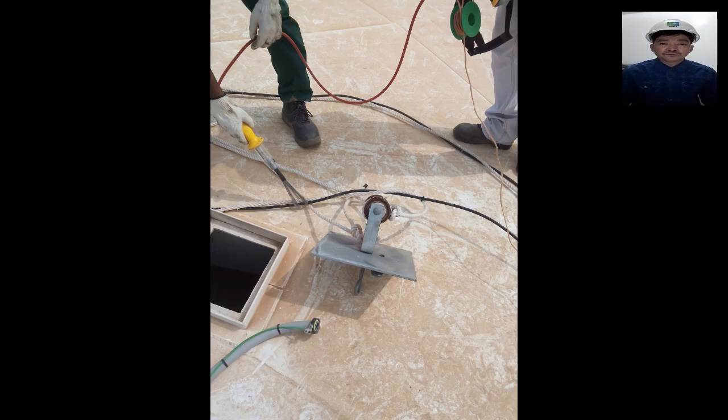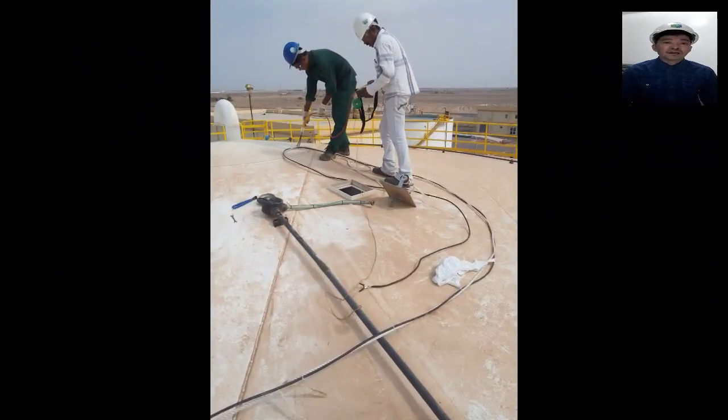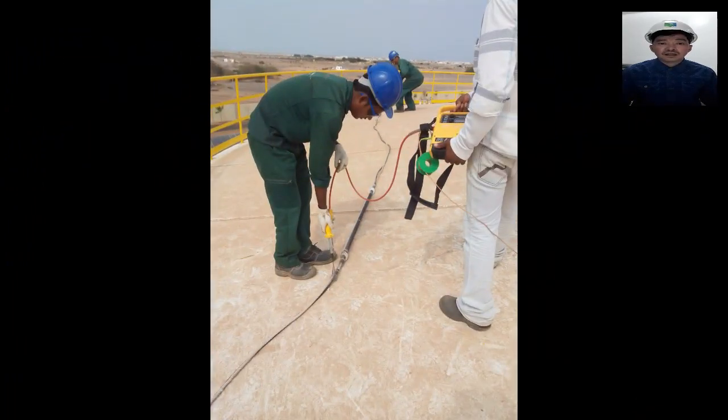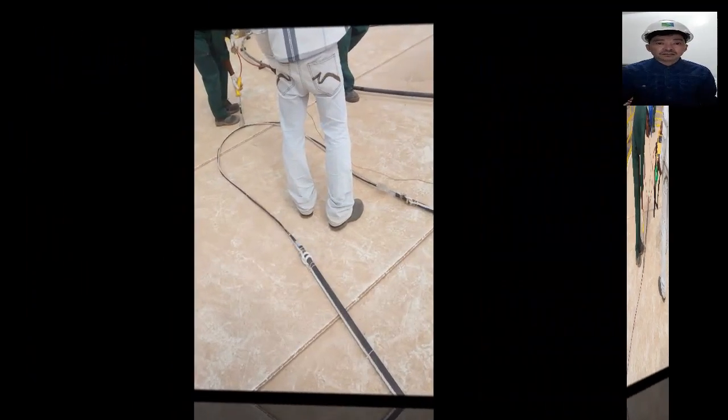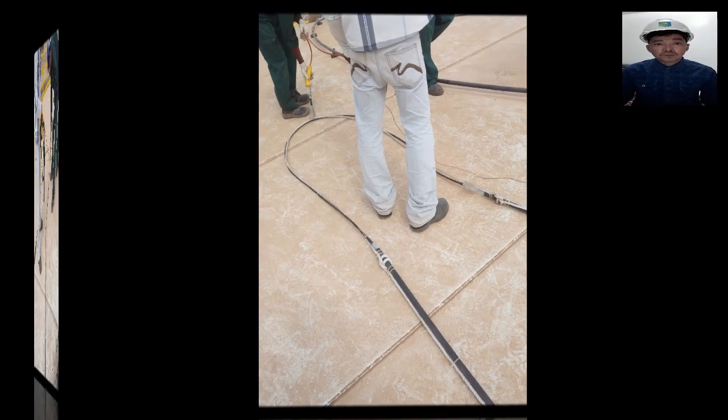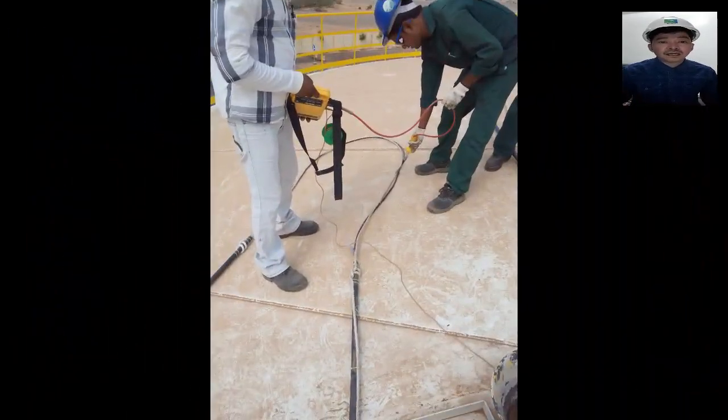That's why during the design, the length of the cable is measured already, and it is as per plan. That's why the distance of the transformer from the tank is normally, or mandatory to be, a maximum of 5 meters unless otherwise previously approved.